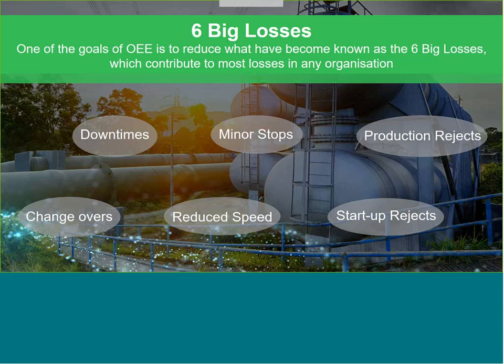Requirements like helping to identify the most frequent downtime reasons. That's something your maintenance team can take away and use to plan out their preventative maintenance schedule. Helping the production engineers to optimize those setup and changeover procedures. That's key to reducing those quality losses. And also helping them to find where is that hidden capacity in the production line.